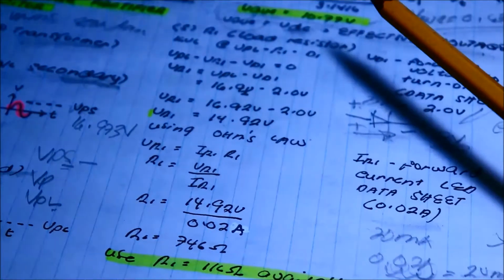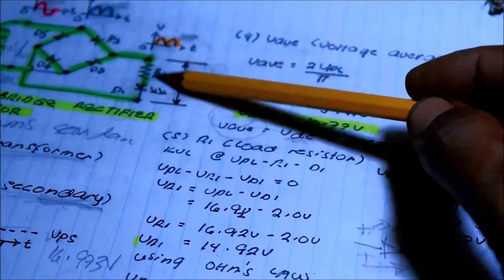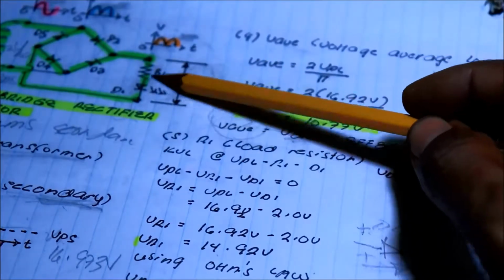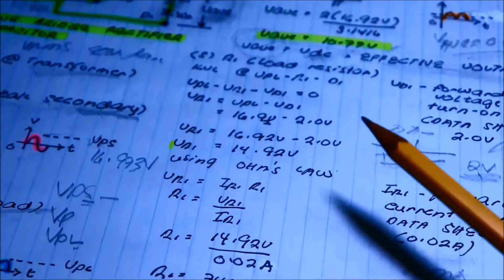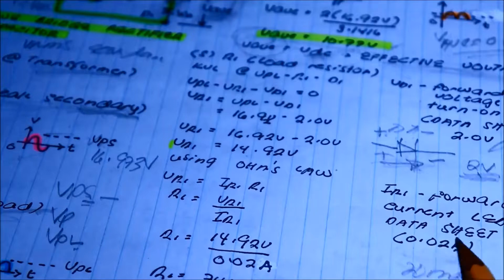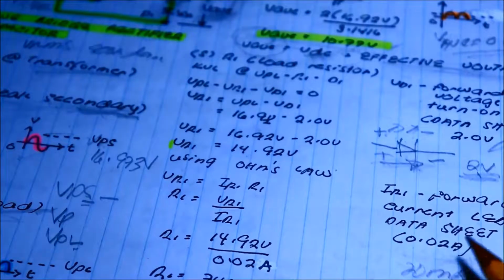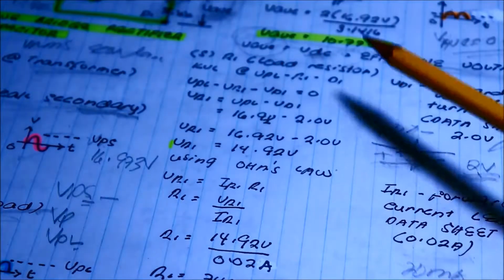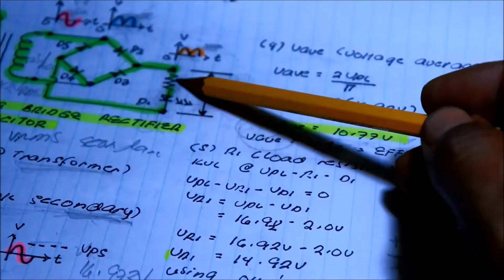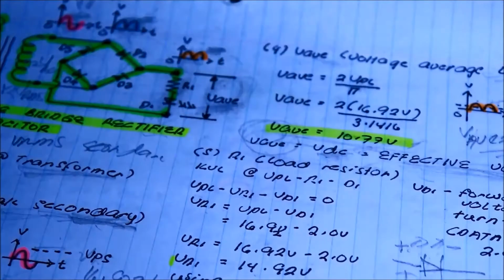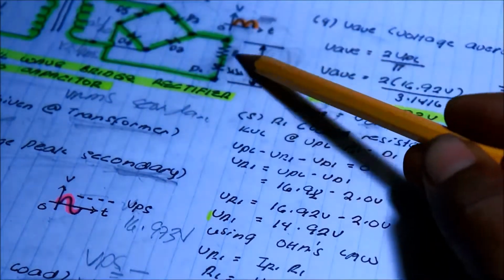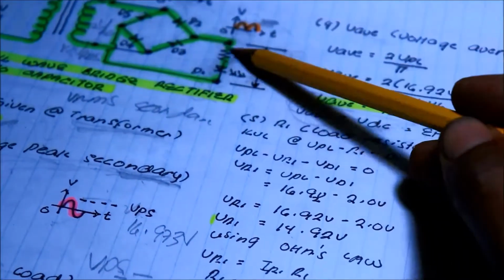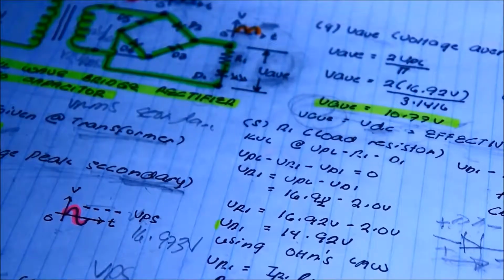And because we don't know the current that flows here, but we know the current 0.02 of the LED. We're designing a load composed of an LED with a current of 0.02. So it means the current that flows here is 0.02. Let us now check the solution to the problem. We're going to compute the value of R1 to limit the current that flows at the LED.